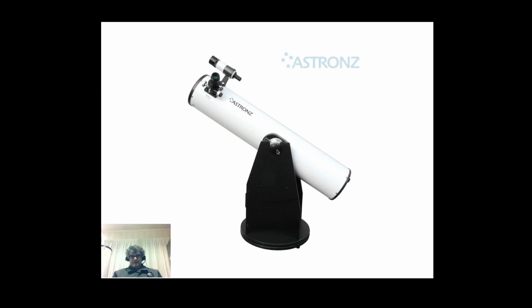But you have an adjustment there which applies tension to the bearing, and again you adjust that to have it tight enough so that it will hold the telescope with its eyepieces without moving too easily, but not so tight you can't move it when you want to move it to a different object. So that's basically the way they work.